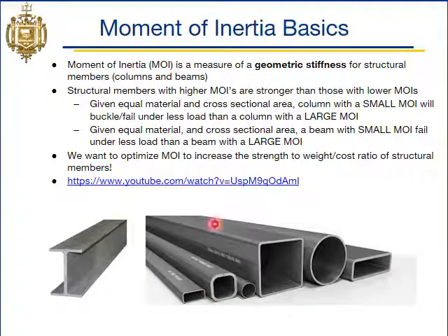Additionally, we have all these structural members here, and you'll notice that all of them are hollow. So what we'll find with moment of inertia is that if we made them solid, sure, it would add strength, but it doesn't really add as much strength as making the structural member thin-walled and really increasing our moment of inertia.